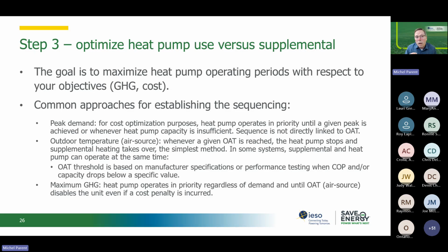If you've got a hydronic heat pump, so if you've got an air to water or water to water heat pump, and you put supplemental heating at the same time, now you can get into conflict where the boilers, which are typically the supplemental heat source when you've got a hydronic system, may be set to provide too much heat into that loop, raising the return temperature beyond what the heat pump can take, and it will shut down your heat pump.